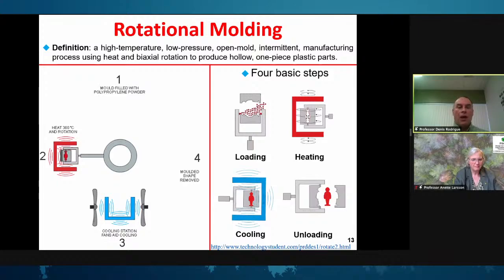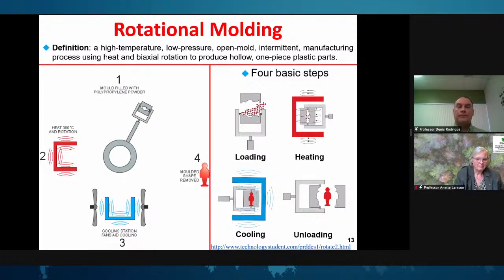Yeah, I think it has been done in the past. Actually, rotational molding started with liquid resins at the beginning because it was easier to mold, and like you said, it can be reactive or not. Again, it's a question of controlling the time and the temperature of your system. That can be done quite easily in a processing system. So yes, it is possible. The problem with the solvent is you need something that will be cheap because you lose it every time. Thanks.